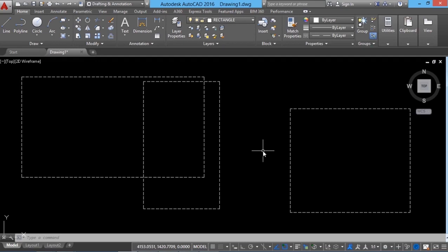When you freeze a layer in AutoCAD, the objects in that layer will not undergo any regenerations, will not take part in any drawing or editing operation, and will not appear in the print. Let's see that. Presently, all the layers except the current layer are frozen.